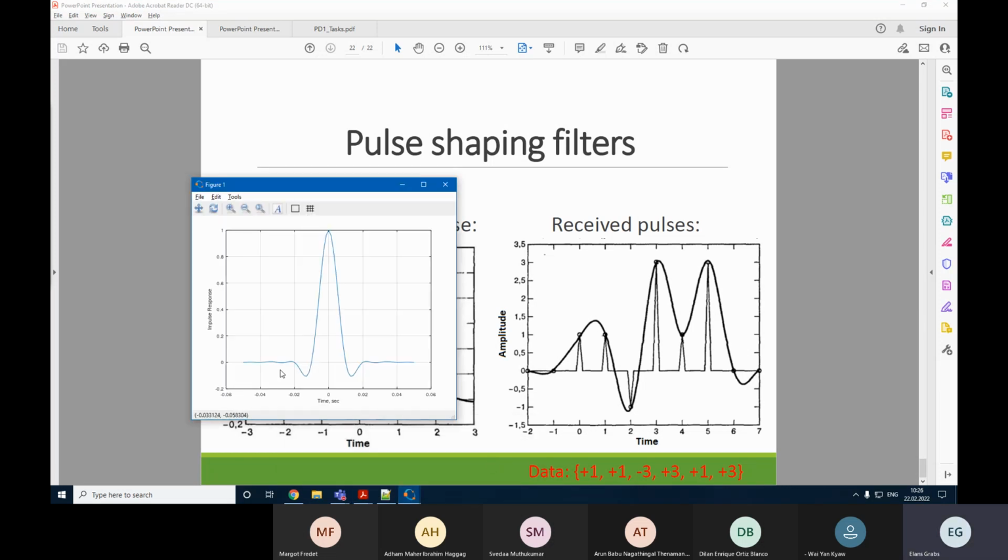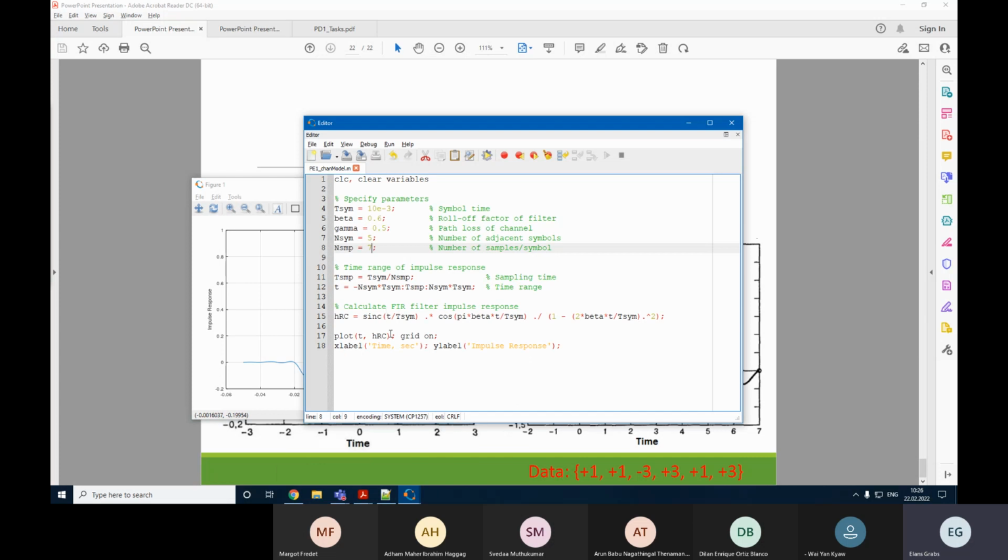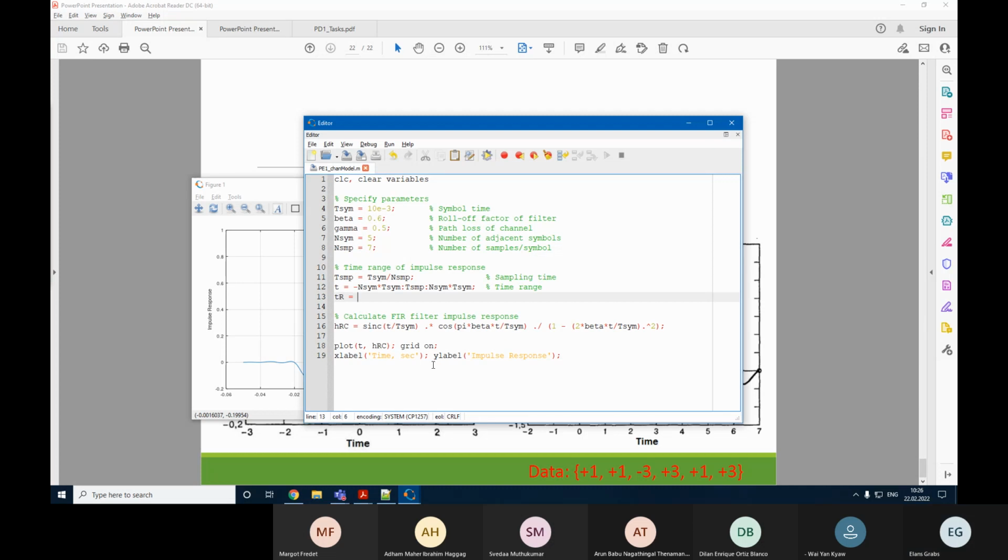Now, this time, however, doesn't really represent correct values. So we need to actually, for plotting purposes, have other time. Yes, so for plotting purposes here, we need to show real time. Let us calculate it accordingly here, the real, as starting from 0 and going up to double number of symbols multiplied by symbol time with the step of the sampling.